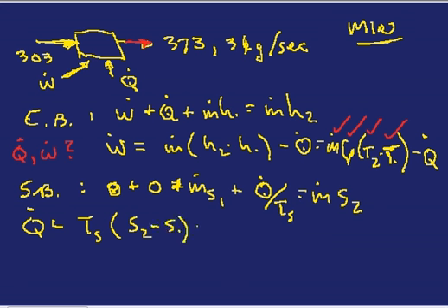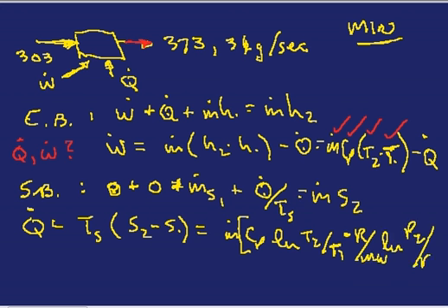And we'll substitute in what we know for entropy of an ideal gas. That would be m dot times Cp ln of T2 over T1, let's put that in brackets, minus R over molecular weight ln P2 over P1. Now, of course, this P2 over P1 will be 1, assuming the same pressure in and out. So the log of 1 is 0, so this whole term drops out.